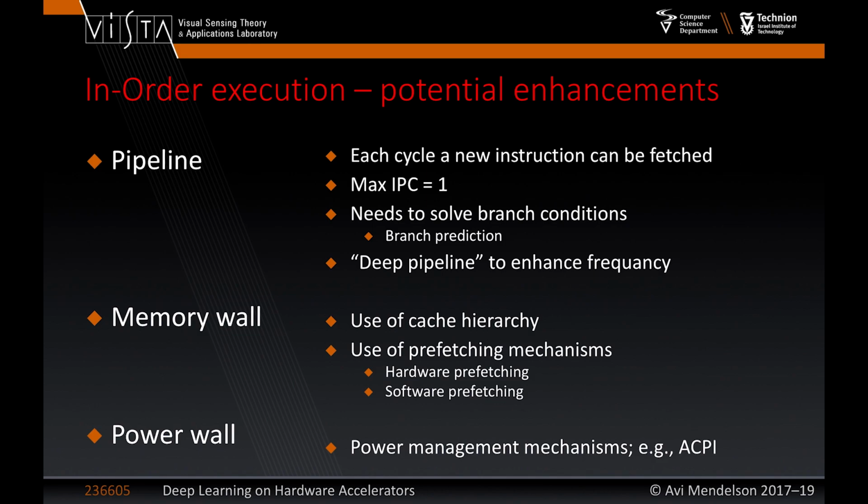And of course, if you expedite the clock rate and you finish every cycle, you're getting more instructions per second. And this is the purpose. But it is not sufficient. Because the instruction per cycle, notice, is not sensitive to the frequency at all, because it is per cycle. It cannot exceed 1 in this example on this architecture.